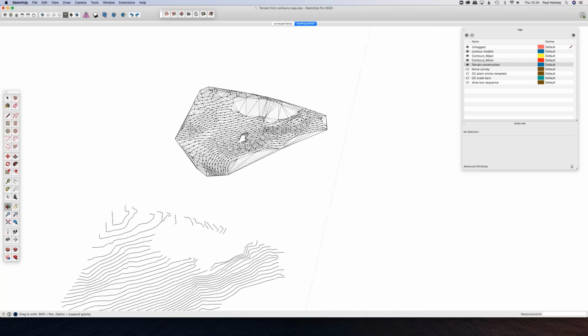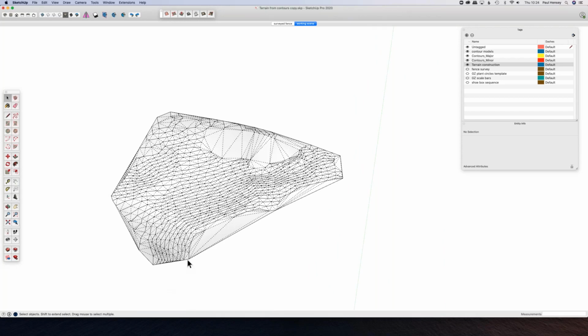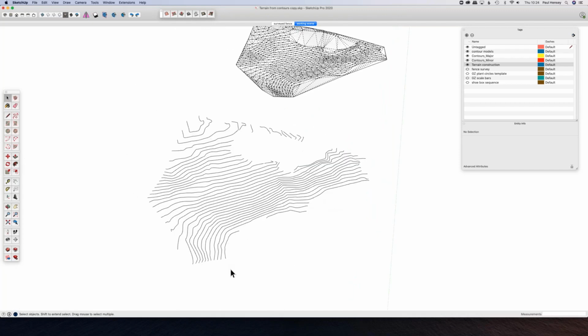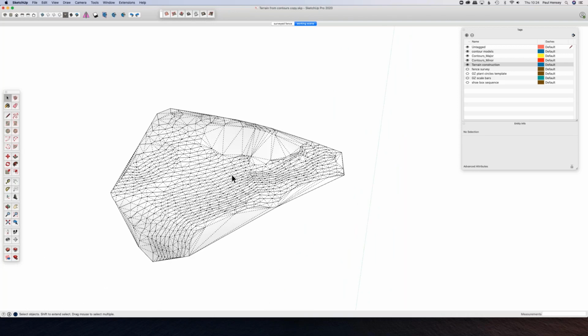What's also important to appreciate with this technique is my terrain wasn't this shape before I put this surface over it. It had these concave sections. And just to look back at the original version, we've got these areas. So it's almost like stretching a balloon over a wireframe.